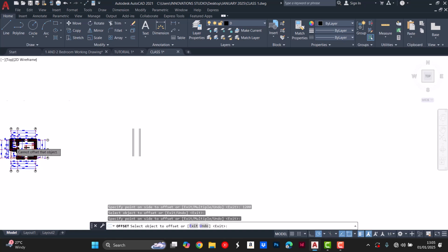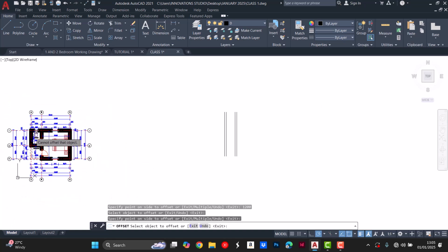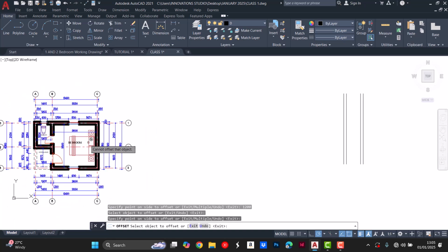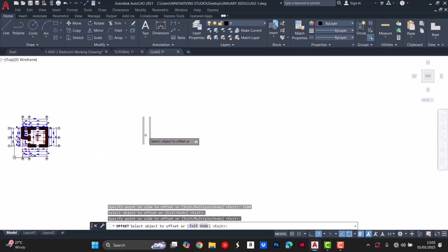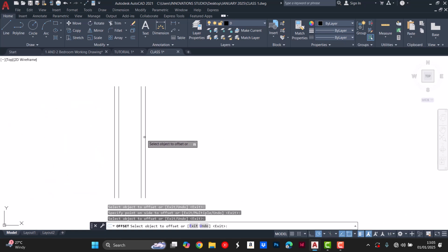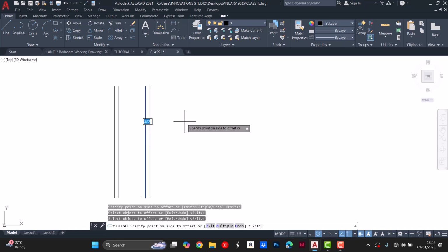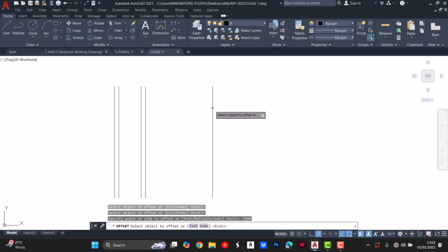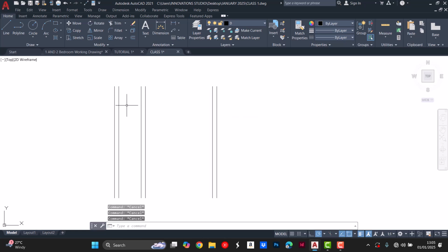Now the wall we just made is this wall. Then we want to make this bedroom space. You click on it, then you click on the line again, then type 3,600. Then you type 230. It's already in 230. Then you press enter. When you do that, you press escape. Then you come back and click on line again.